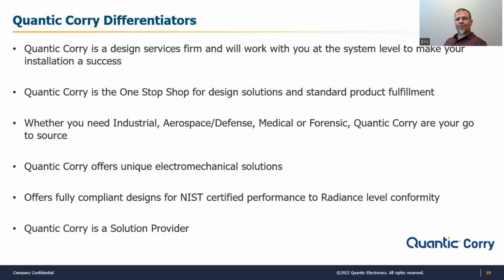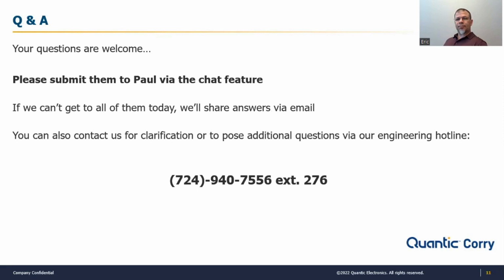Excellent. Well, thank you. I think we have time for one question. You had mentioned earlier some of the differences between active and passive. Why would somebody choose a passive filter instead of an active one if the passive ones are not quite as good? Well, cost would be a big reason to choose a passive filter. The passive filters typically are a little less costly and smaller, but they do not provide the isolation that an active filter provides.